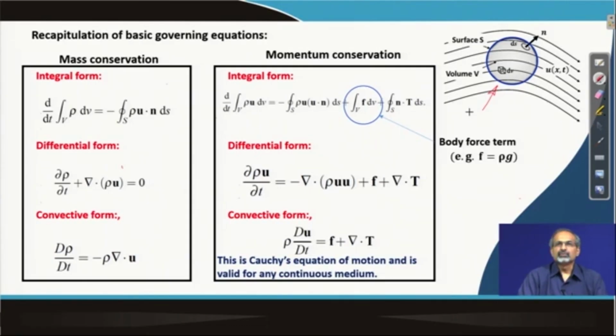And in general, we would assume that there is a velocity field, which is a function of both space and time, which is moving through this region, and we would assume that this region is fixed in space. So, that is typically what we do in the Eulerian approach, and we try to monitor the flux of different quantities across the boundary of such a control volume, so that we can develop the respective conservation equations, which involve mass, momentum, and energy.